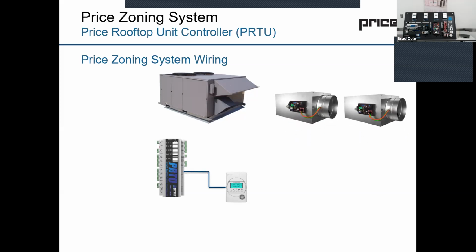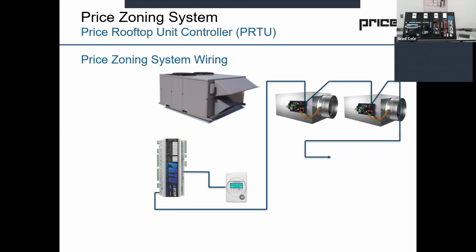From there, the sheet metal guy or the mechanical is going to hang the boxes that come from Price with a controller on it, already factory mounted, ready to go and pre-programmed. So that's great. Couldn't get easier. And then what we do is we give you the cables to click and daisy chain the BACnet network together with these 35-foot cables that we provide from Price.